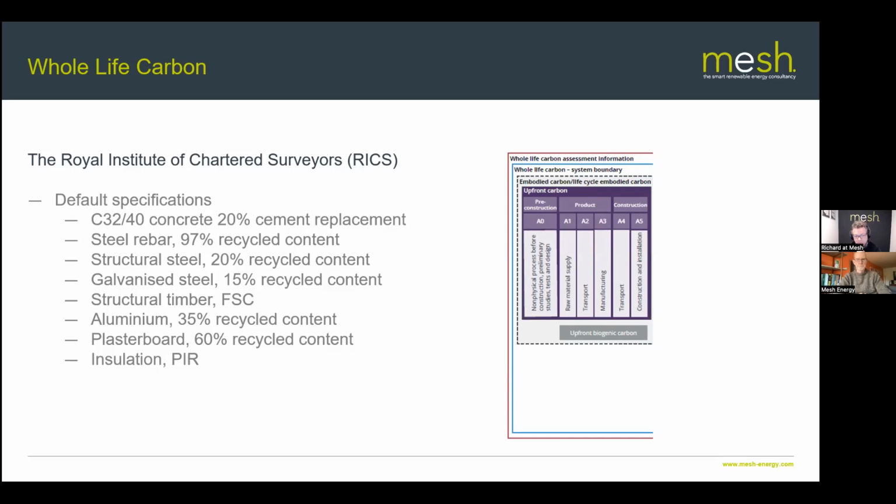But it is worth bearing in mind that as we start to use more recycled content in concrete, for example, it will start to extend the curing time. So, on the one hand, you can use recycled aggregate, but on the other hand, when you get to your stage 5, your construction program might extend slightly. But of course, all these materials, like I said, have more and more recycled content available now. So, there's plenty of alternatives.